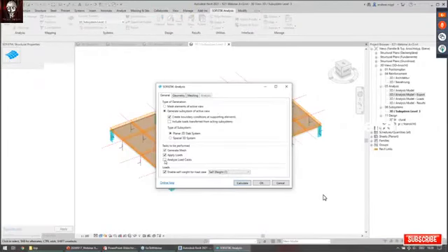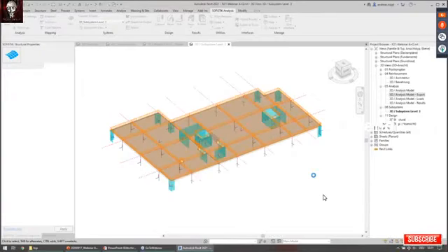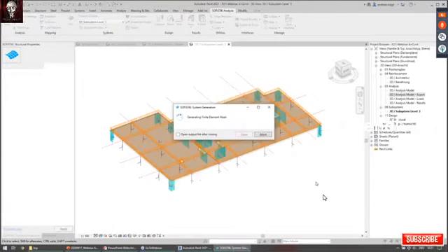The same dialog shows up with one extension. For example, you see that I now create boundary conditions at the supporting elements. So instead of exporting these downstanding members, these columns and walls, as elements, we are creating boundary conditions based on the stiffness of these elements. It takes some seconds to analyze all these different pattern loads.